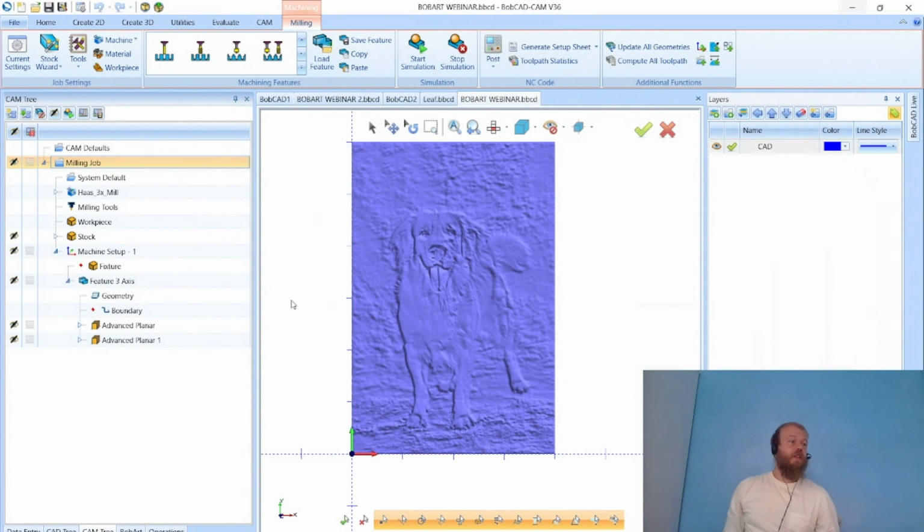So yeah, and then one other thing, as Bob mentioned, if you wanted to try it out, you can get a part, place it on a piece of printer paper, and take a picture of it from the top down. Make sure you don't have any shadows, and then try to vectorize that around the profile of the part. And then you'll have to dimension it out. But it could save you some time with Bobart. Instead of sketching the drawing out, you can start with a sort of template like that from an image. But yeah, let me know if you guys have any other questions in the Bobart module here today.